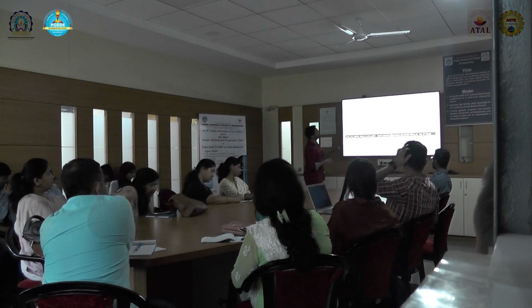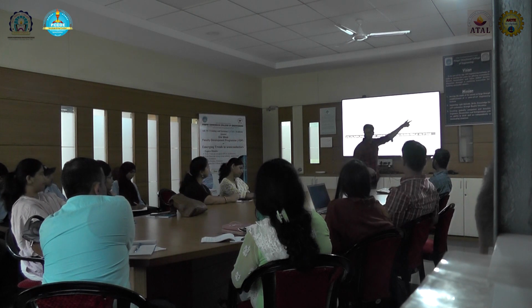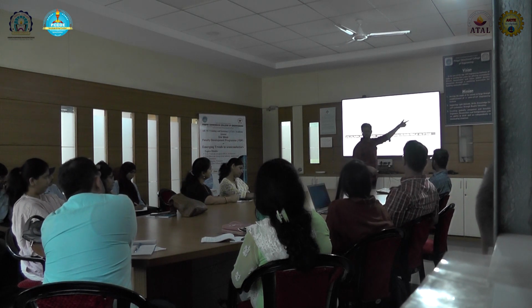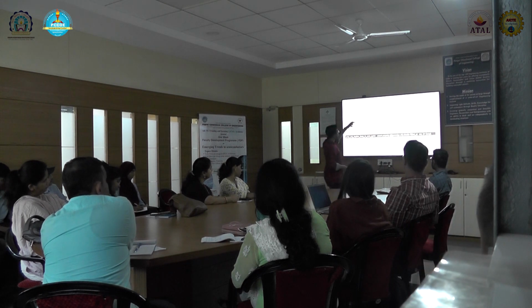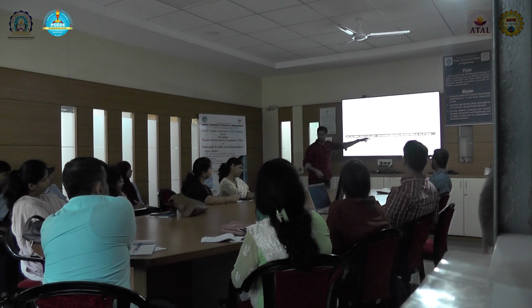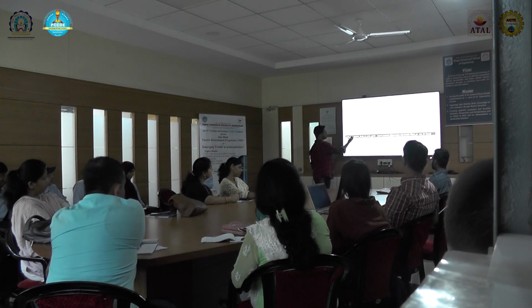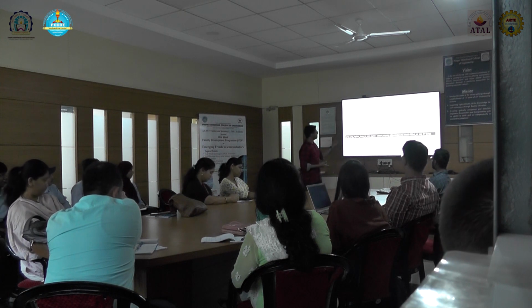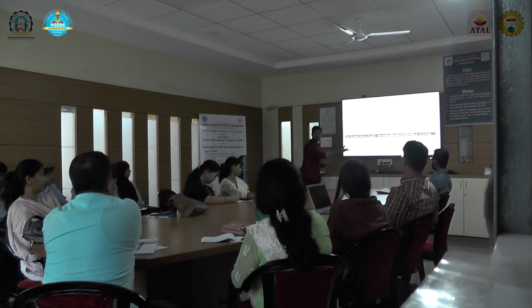As you can see, in the same protocol, once you get a request, busy gets high. So we will write a property for this scenario. Once you get a request, busy is getting high. So how do you write a property? First, the name of the property. It can be anything you want, like you can simply write rec next busy. But we write meaningful names because it's easy for a person to understand what the property is doing.